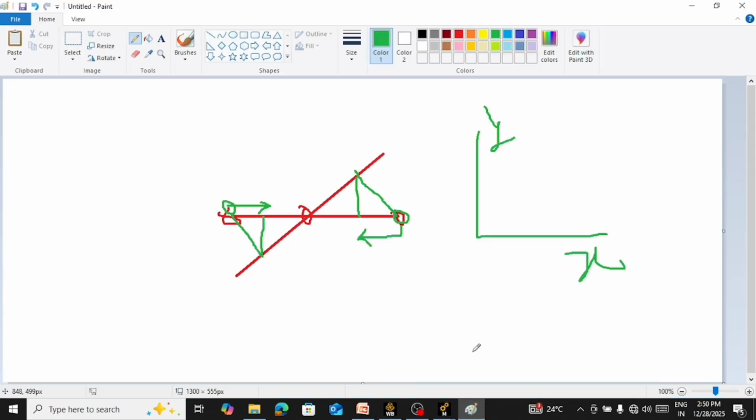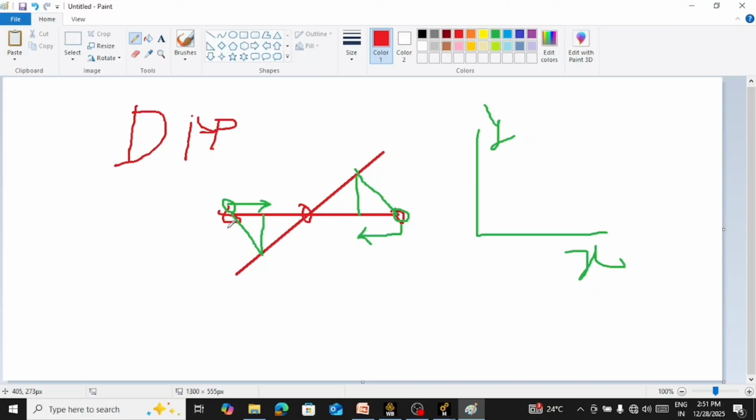And why is this not coming in the remote displacement? If you want to understand, we have this as a displacement condition. Now if you look at the remote displacement case, as I have told you, one RP is created at this point, and these nodes have a constraint equation with respect to this RP point.